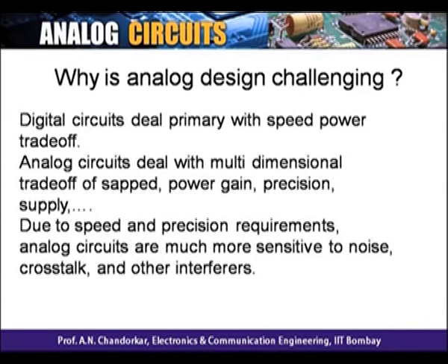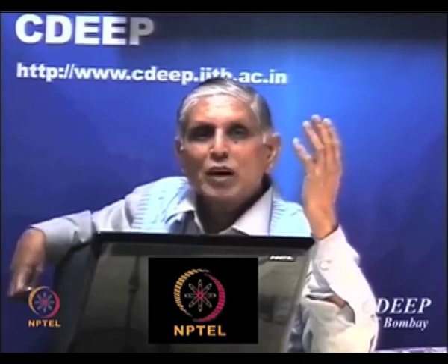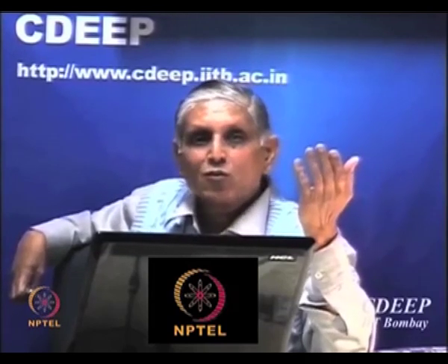So the whole research right now is how to reduce the power, but there is a trade-off. As soon as I reduce the power, what do I reduce essentially? The current. If I reduce the current, power will go down, V into I. But if I reduce the current, the time taken for the capacitor to charge with the lower current will be larger, C dV by dt is smaller, so t takes longer. Okay, speed is gone. So there is a trade-off.